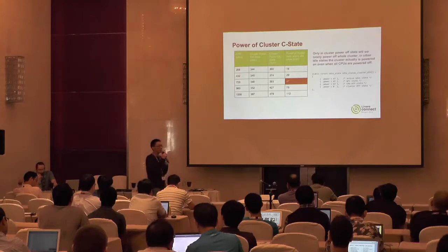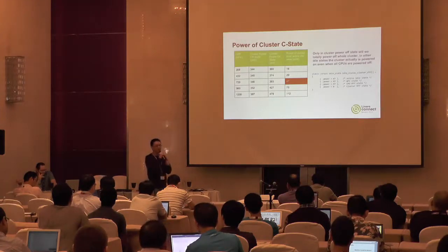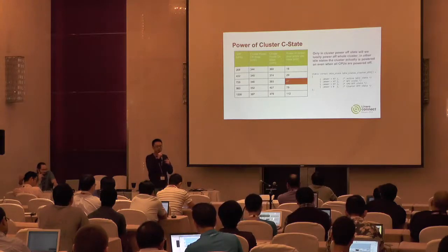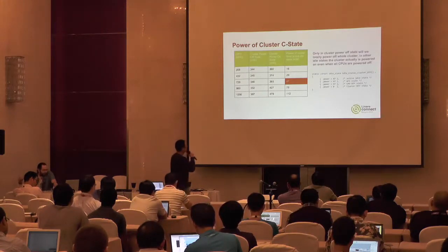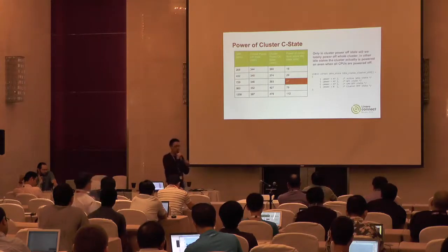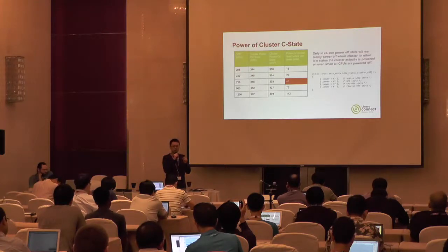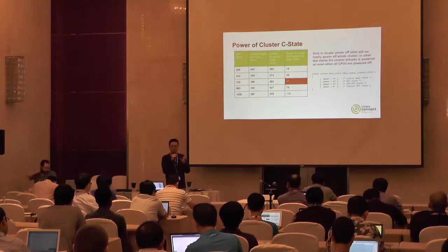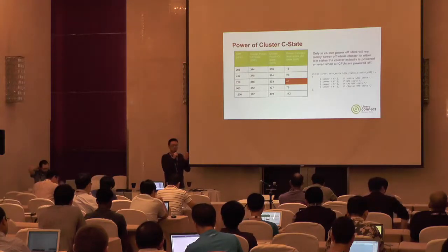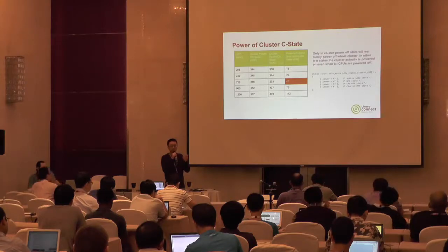When we generated the power data for the cluster level power state, we need to generate the active idle state. If we think that there is a low CPU running, but in this case the cluster level is actually being powered on and the clock has also been provided for this cluster. So for different operating points, the power data for the cluster level is quite different.